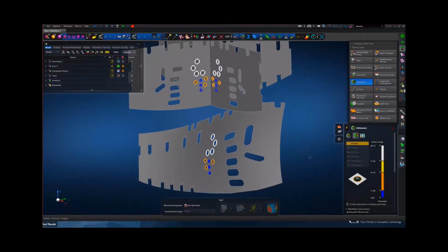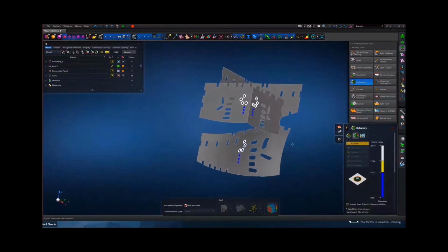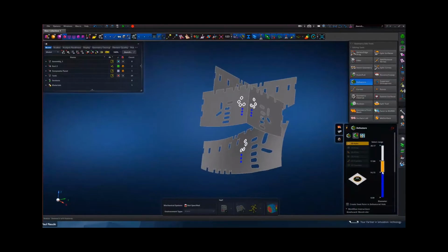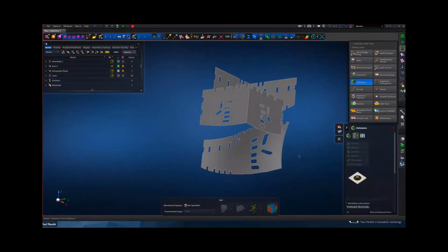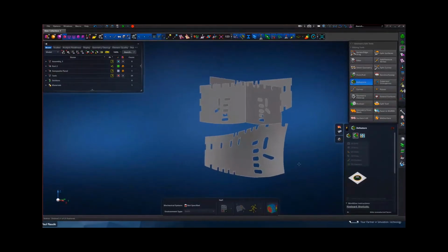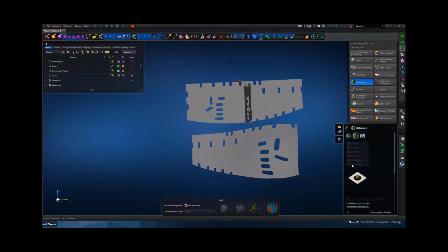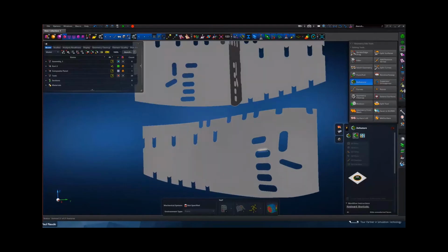So you select them, it turns orange, and orange means that if I now middle mouse click, the selected entities will be removed. And as you can see, they were removed on all the faces. Now, if you just want to remove all of them, you simply select it in this manner, and there you go. All those holes are removed. Okay, but those only selected or pre-selected standard features like holes, and on solids it will also select fillets and chamfers. What about all these others?